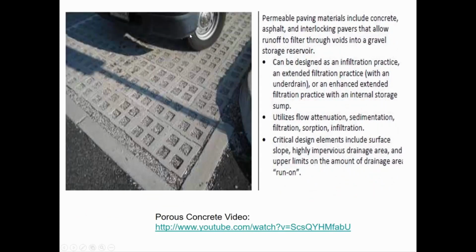So here's another one. Trying to make it so that concrete absorbs more water than it ordinarily would. One approach is to use concrete pavers and packing gravel in, where it used to just be a continuously impervious surface. Now you've got a little bit of impervious surface with the paver, like this might be a cinder block that you then reinforce with gravel. And so there's going to be better infiltration there than there would be for pure concrete.